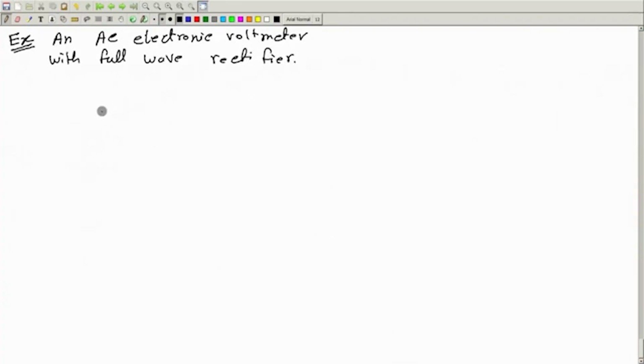Let's take some simple idea and then we will refine it. We have an unknown voltage to measure, call it Vi, and we assume this is small, so we will amplify it. To amplify it, we can take an inverting or non-inverting amplifier. Let's take a non-inverting amplifier.